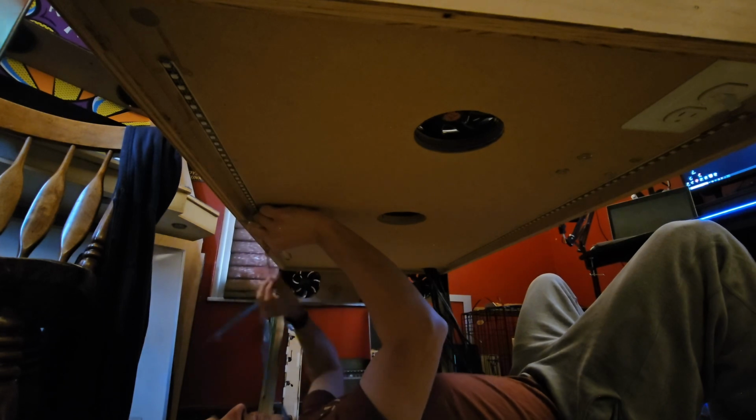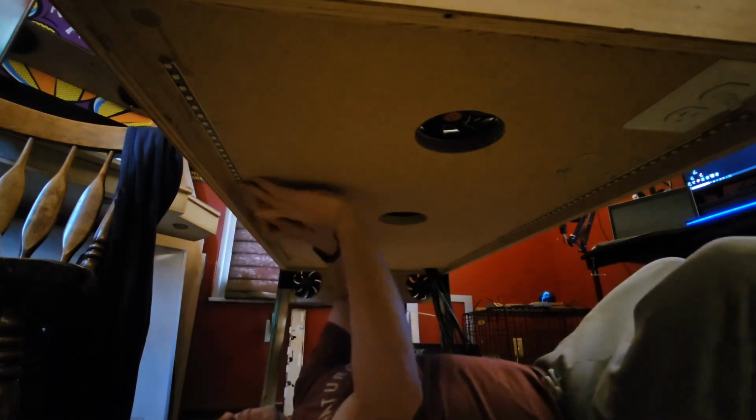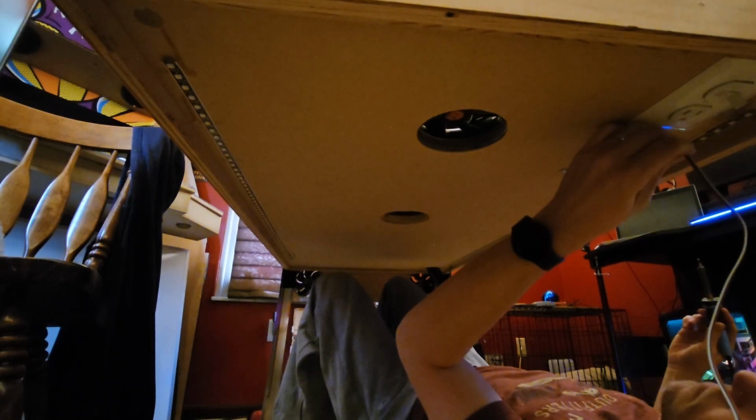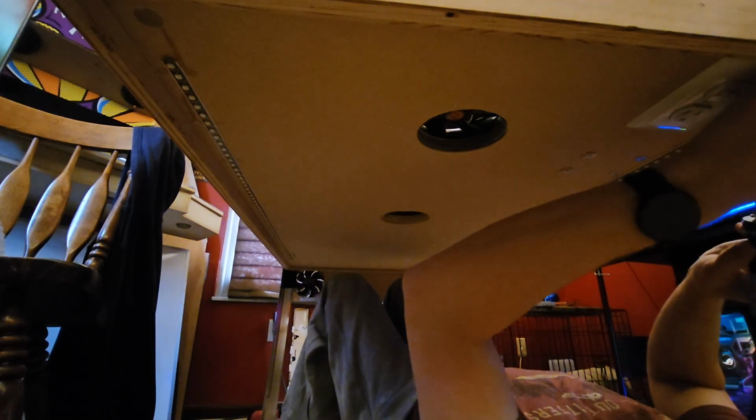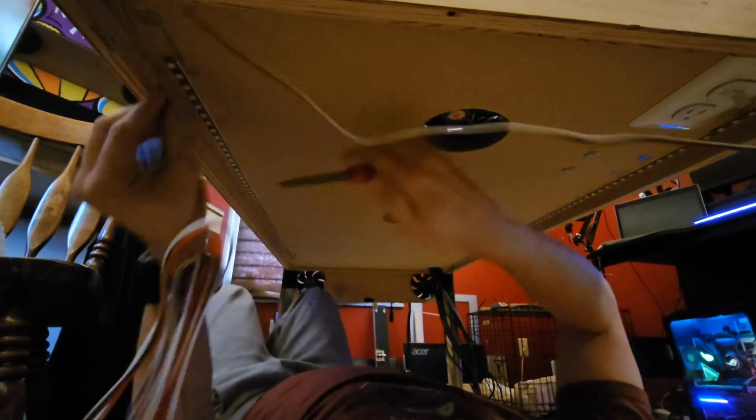These two pixel strips are not just two individual 62 strips. We're going to do a daisy chain. So in the software, we're going to have a left side and a right side, but in reality, it's just one really long strip of LEDs that is 124 pixels long. So as I'm putting this on there, you're actually following the flow in which the number of pixels are. Pixel 1 starts in the back right-hand corner, comes all the way down to the front switch, and then pixel number 63 starts in the left front corner and goes to the back. That's the flow, and in the software, we're going to fix everything and set it up so they're two individual strips, but in reality, it's just one.